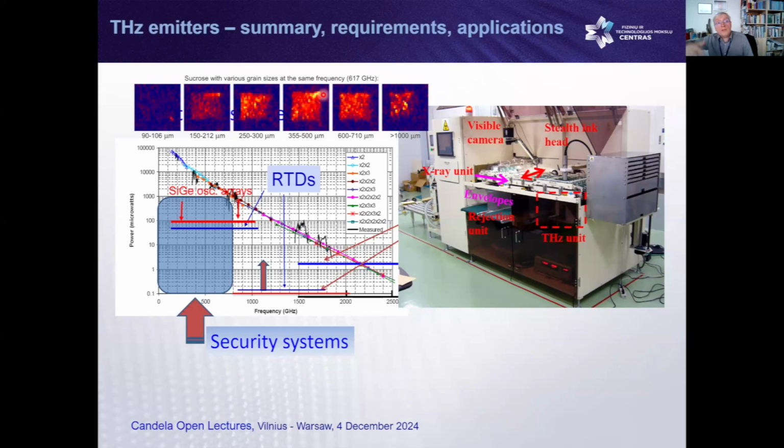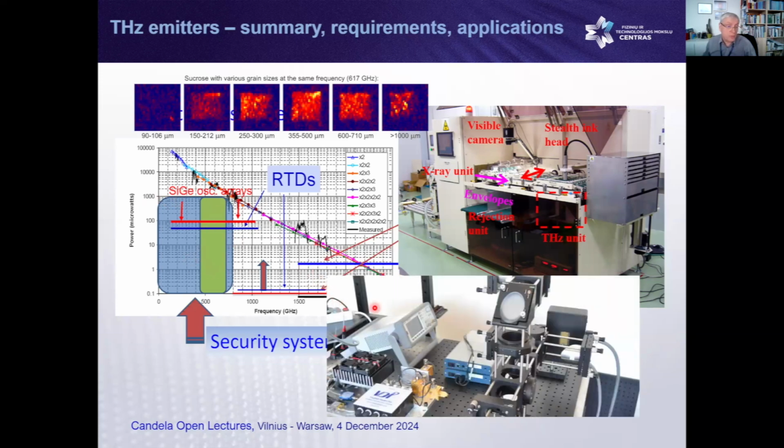If we go to lower frequencies, we have a cheaper system, but the accuracy is lost. If we go to higher frequencies, we can get better quality, but the system becomes very complicated, expensive, and relatively hard to record because powers go down. So in fact, around 0.6 terahertz is a good rational option for security systems. That is why all people are looking around this and going to 1 milliwatt, which is an absolutely rational number for emission and for implementing the system.